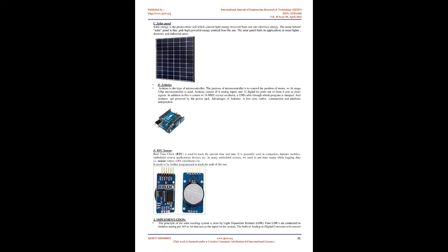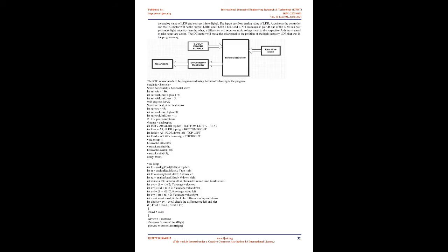They were addressed in this paper, where the user can determine the frequency and where the panels should move based on a pre-programmed preset threshold. This preset is user-defined. The study has also shown that it is not necessary to track the altitude angle in areas on either side of the equator continuously where the altitude angle does not exceed the 30° like our area, Bahrain, but it would be better to do an offline tracking where 4 to 8 movements of 8° to 10° each per year are largely sufficient, and more than 98.36% extraction could be harvested compared to continuous tracking.